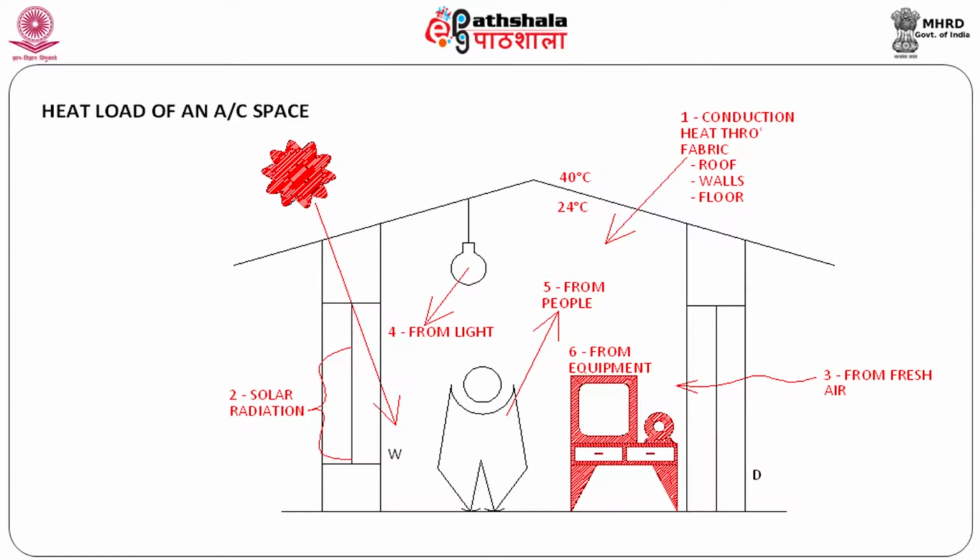The internal factors are basically any equipment that you keep inside. Second, you yourself, a person, by virtue of being at 38 degrees centigrade and sitting in a room of 24 degrees centigrade, always heat up the room. He perspires, so he adds latent heat. So, a person adds heat, and apart from it, one of the most basic things is lights. The moment you have light, the light ultimately gets transformed into heat, which the air conditioning man is obliged to collect and take out of the room.